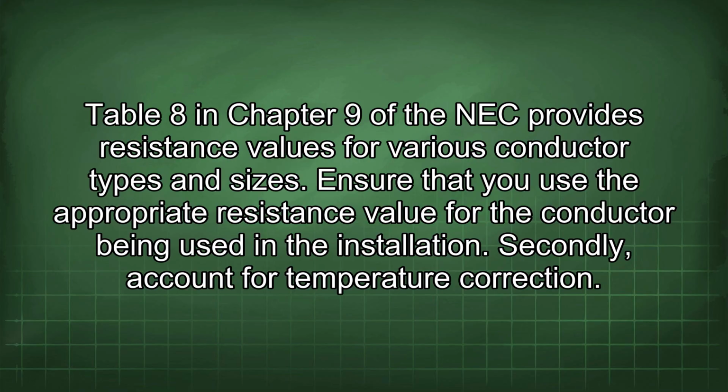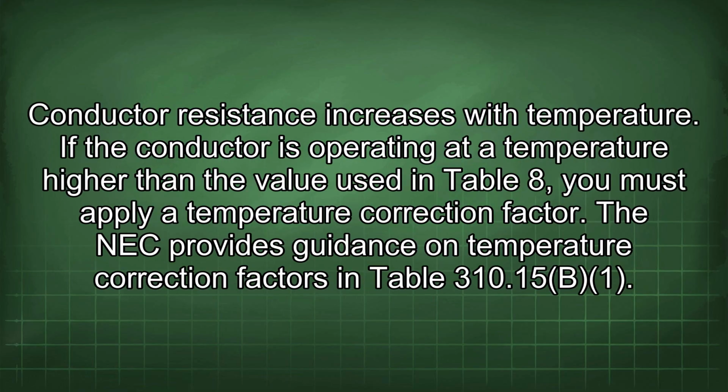Secondly, account for temperature correction. Conductor resistance increases with temperature. If the conductor is operating at a temperature higher than the value used in Table 8, you must apply a temperature correction factor. The NEC provides guidance on temperature correction factors in Table 310.15(B).